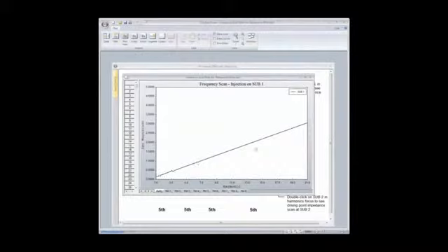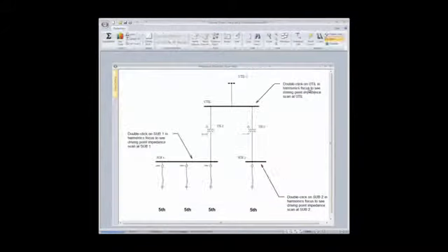Well, basically a ramp, and the impedance buffering now has kept the filter on that other bus from really manifesting for us on the bus where we're doing our impedance scan. Also, the driving point impedance, the stiffness of this utility source, is helping us as well. So we have this buffering, and on top of it, we have a stiff connection up here helping to isolate these two systems. So buffering impedance, very, very critical and important for us.